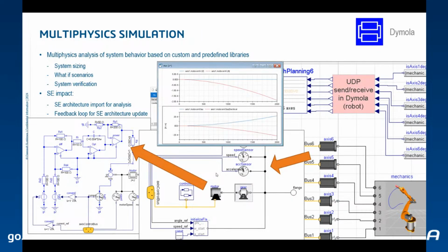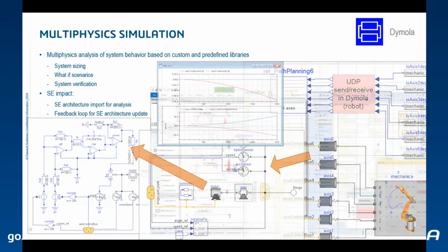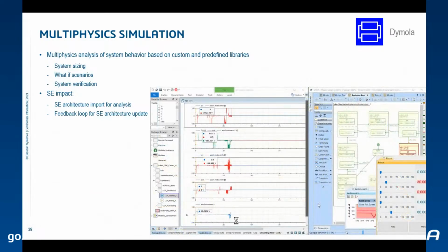So for the motor testing, we use multi-physics simulation with Dymola. Here you see a robotic arm sample. We have the joints, and every motor can have alternatives based on libraries. We can choose more powerful, less powerful, and run through scenarios, and we set the target of the robot, and then we get how fast it will reach the target. Will it reach the target at all? Will it be powerful enough to lift the longer arm? And we integrate with CATIA Magic,